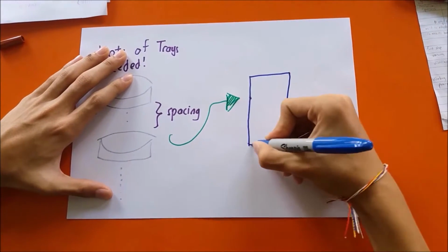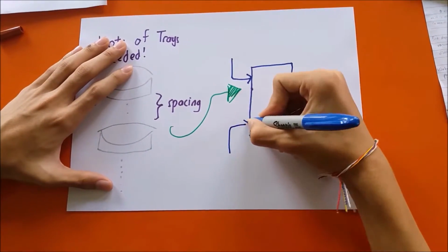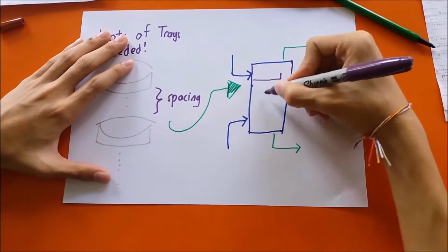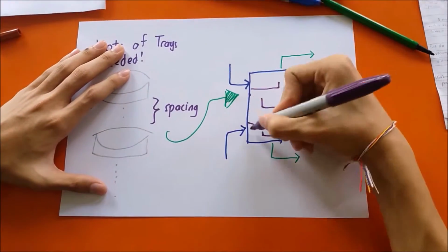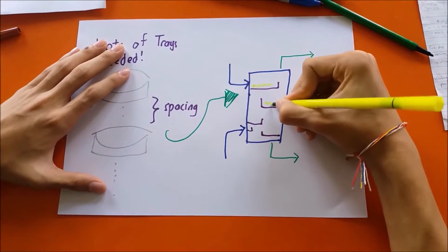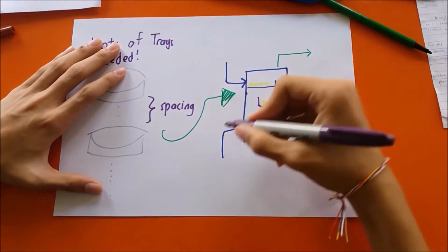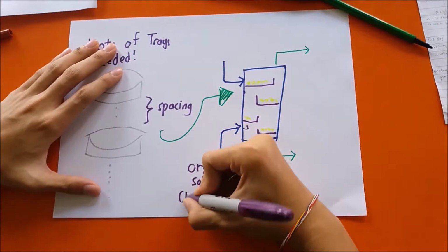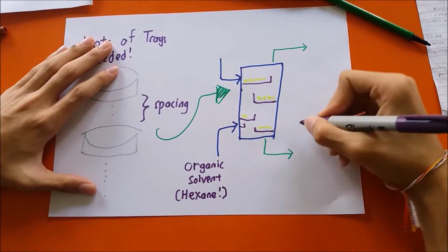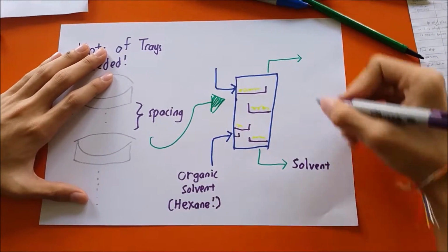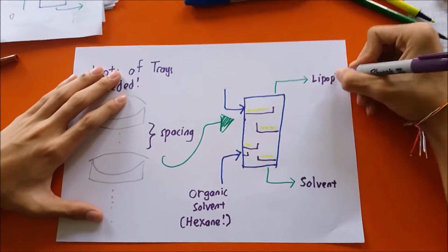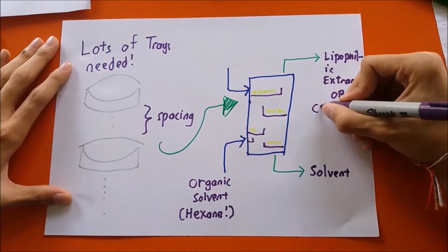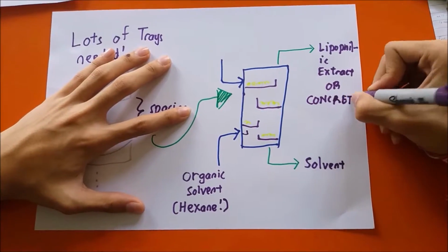The perforated trays are within a removable cylindrical basket. Be careful while stacking the flowers so as to not damage them. Damaging them will cause enzymes to be released in the flower juice, which reduces the quality of the concrete. The basket stacked with flowers is inserted into the extractor, and the hexane is introduced from the bottom into the extractor until the material on the perforated disc assembly is completely immersed. Four to five such washes are given until the material is exhausted.